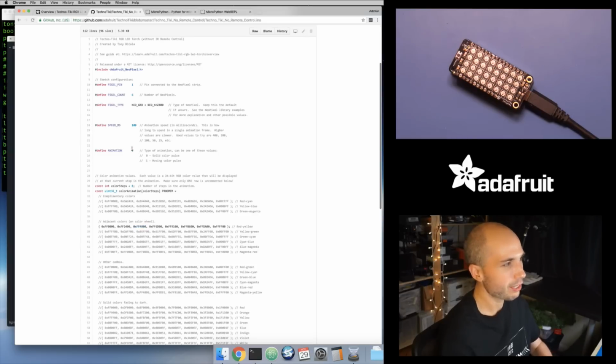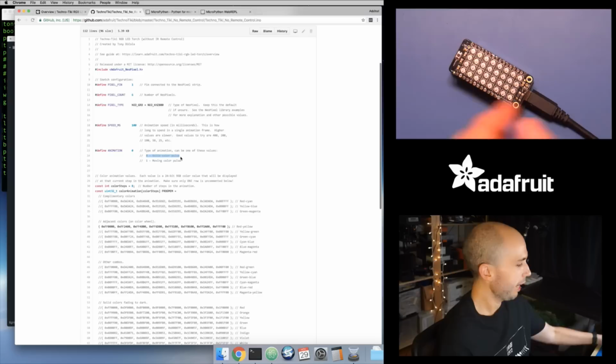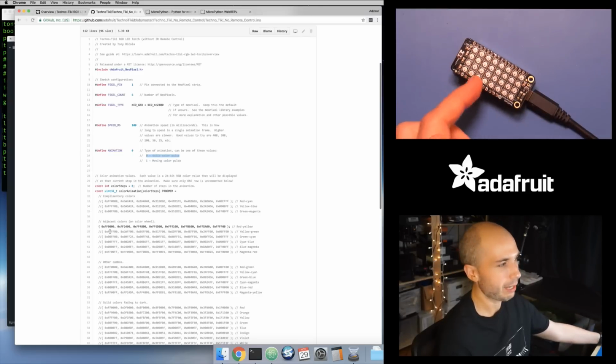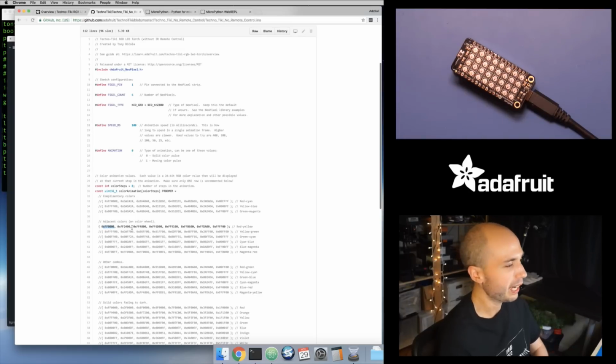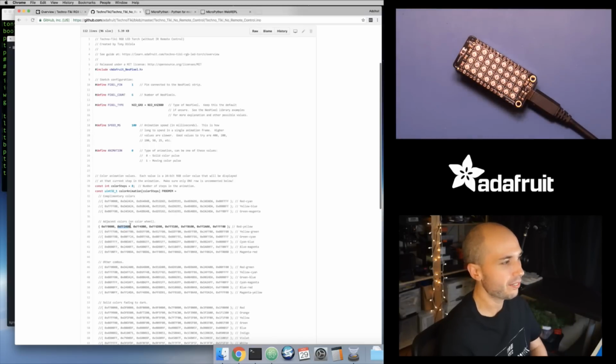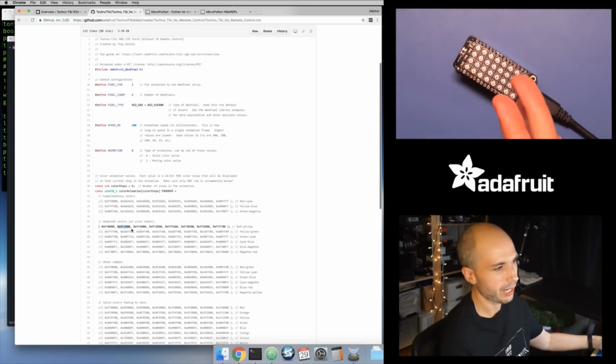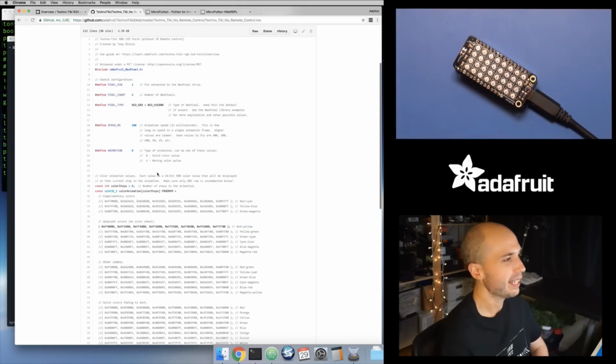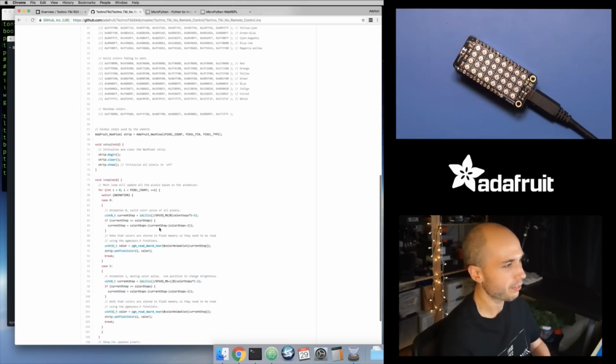And in animation 0, the solid pulse animation, every pixel will be lit up that same color. So in the first step, everything is red for this color. This FF0000, that's a red color for this animation. After 100 milliseconds, every pixel will change to the next color. So this FF24, that's like red that's slowly turning into a yellow color, if I remember correctly here. So that's how that first animation works, the animation 0.